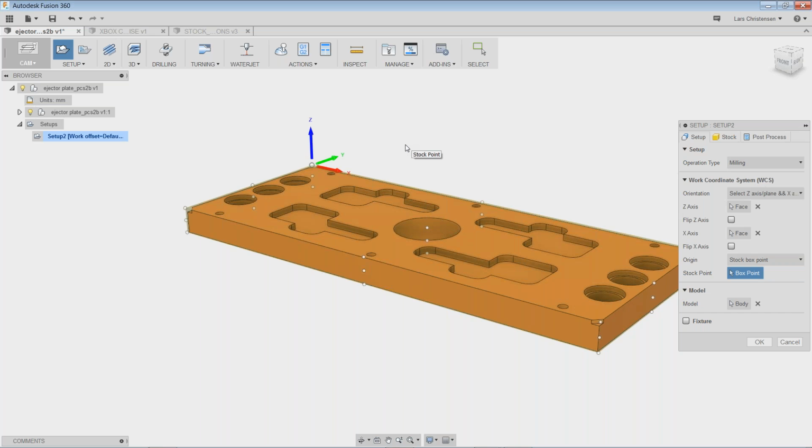The reason this is my preferred corner to pick up a part is that then I'm selecting the same edge here that is resting against the solid jaw on my vise, and I'm not risking any movement. The jaw that is tightening on the part on this end actually has a little bit of movement in it. But I also know one guy who always selects this corner, because then his X and Y are always showing plus in his code, and he preferred that. This is really a preference thing, but again, my choice is normally selecting this upper corner here.